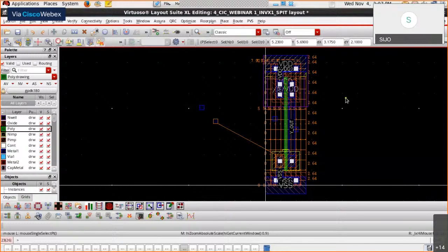I think you are a little bit confused here. We don't have a different layout for each corner, madam. Corner comes when it goes to fabrication. Suppose you have designed the same inverter, next it goes for fabrication. When it comes to fabrication, then only we will characterize it as different corners. All your transistors will not be in the same corner. That's the idea. Depending upon each corner, the performance also will vary.